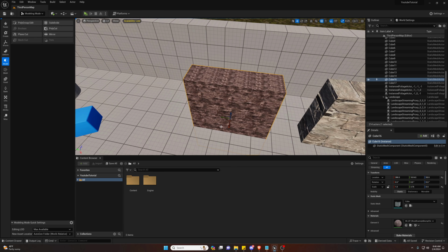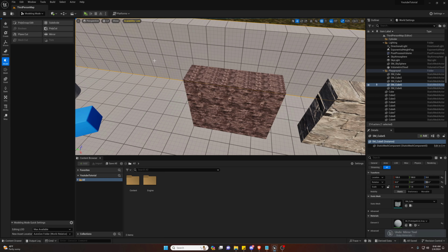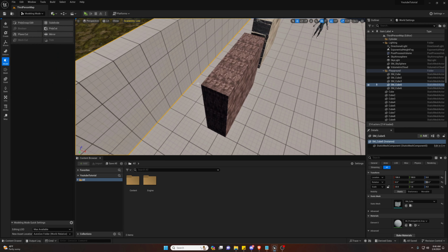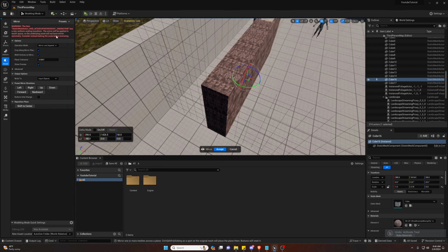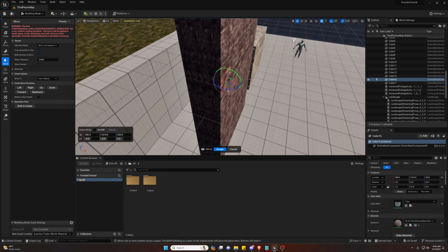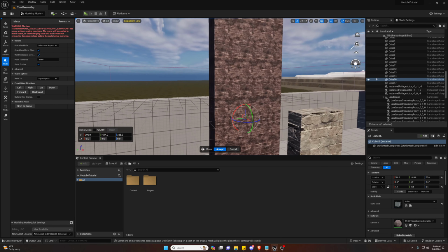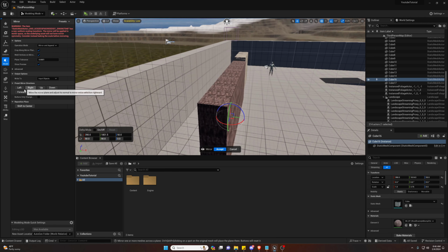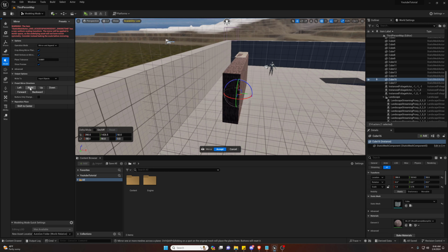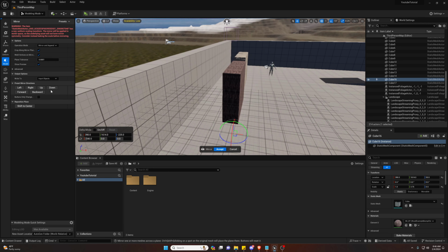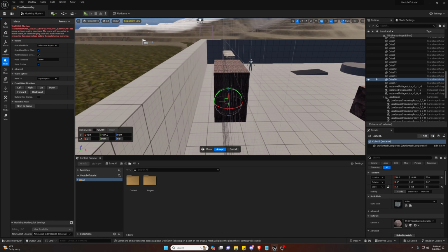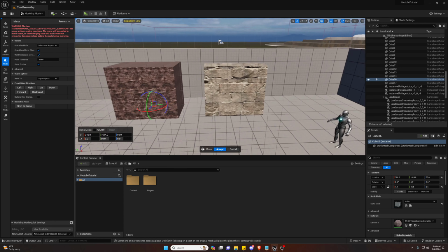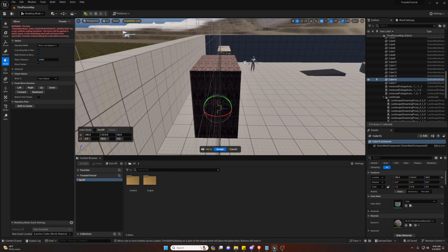Now what else we can do with this tool is go to our mirroring button. Oh, selected the wrong cube there. We can go to mirroring. We can actually do exactly what it says and mirror the object in different directions of symmetry to the object. And it attaches it to the mesh itself, so it becomes part of the object, which is pretty neat, pretty cool for creating quick new objects out of other objects.